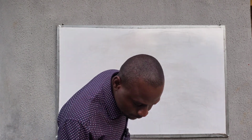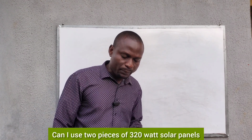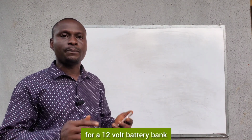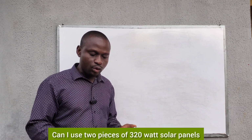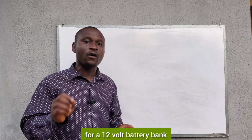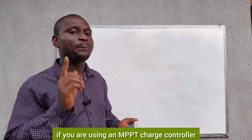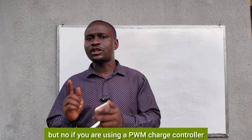Then we have question number 7. Can I use 2 pieces of 320 watt solar panels for a 12 volt battery bank? The answer is yes if you are using an MPPT charge controller, but no if you are using a PWM charge controller.